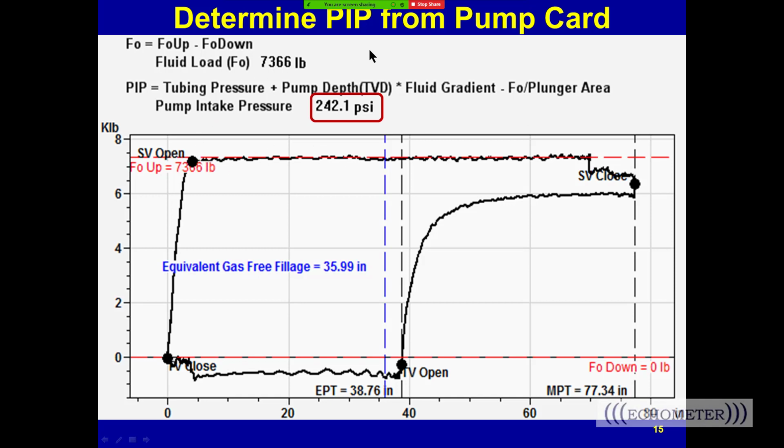If the pump card is concave outward, that just means that you haven't accounted for the excessive damping from fluid on the rod string. The damping factor should be increased. But damping factors don't fix mechanical friction. And that's all discussed in the second presentation we did on forces not accounted for by the wave equation on Ask Echometer. So if you're curious about this question about mechanical friction, damping factors, please review that Ask Echometer presentation and feel free to email us questions about that.